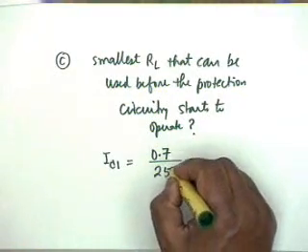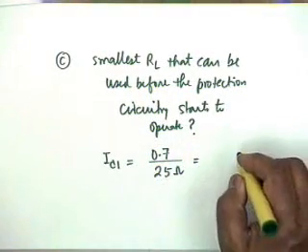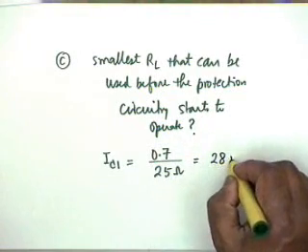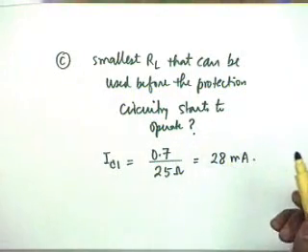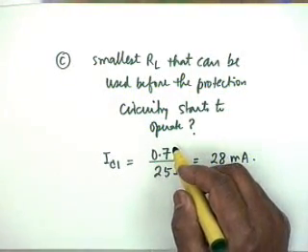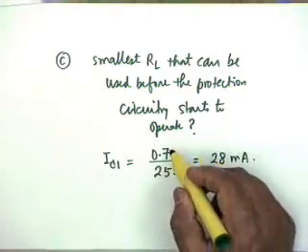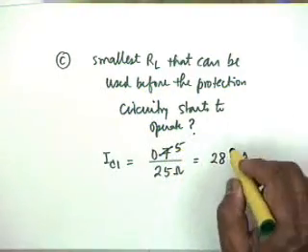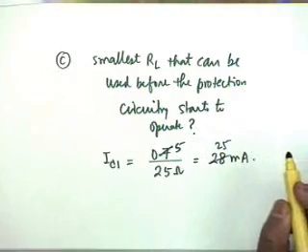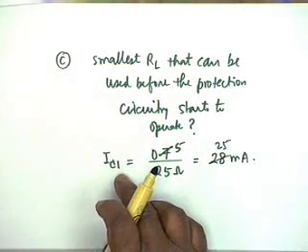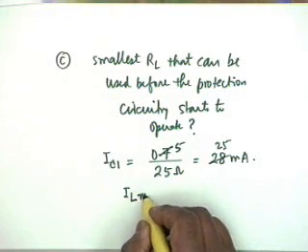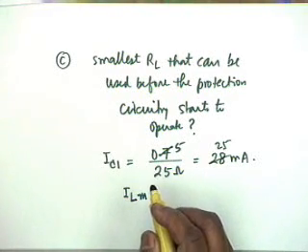That is equal to 28 milliampere. All right, take 0.5. If VBE on is 0.5, we have taken this figure as 0.5. If this is 0.5, obviously this will be 25 milliampere. Now, if IC1 is limited to 25 milliampere, it cannot increase beyond that. Obviously, this must be equal to the maximum value of the load current, ILM. Agree? So ILM is equal to 25 milliampere.